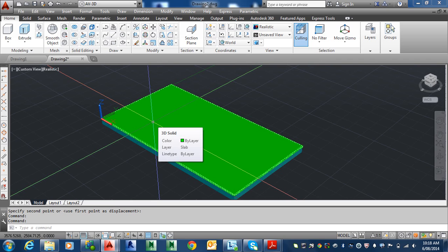So that's 160 wide, because basically this is a brick veneer home, so there's 110 for the bricks, and there's a 50mm gap. And then the timber frame starts inside, if you know the general construction of the house. So we need to have a 160 rebate, which is a 50 plus the 110 for the brick, along the perimeter of the slab.